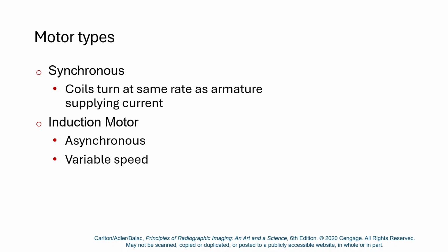All right. And so DC motors are synchronous motors, or can be made into synchronous motors, and synchronous motors spin at the same rate as the current. Well, that's not a DC motor, excuse me. That would be an AC synchronous motor. An AC synchronous motor spins at the same frequency as the AC current. So at 60 hertz, you get 60 rotations per second. That means the synchronous motor can be used as a timer, and early timing devices were synchronous motor timing devices.